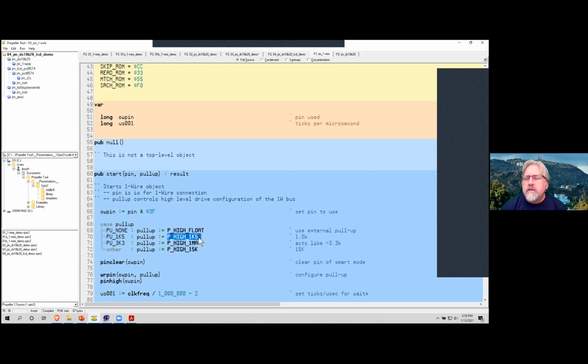And I guess technically you could. If you could see the bus, you could watch the transactions and know what's going on. But it would take a special piece of hardware. It's not like you can clone an RFID card. There's no way to program one of these iButtons. You would have to make your own kind of thing rigged up to a microcontroller that would spoof the serial number that you'd captured. So it's doable, but it's more problematic than the RFID thing, which is probably one of their selling points for security with these things.